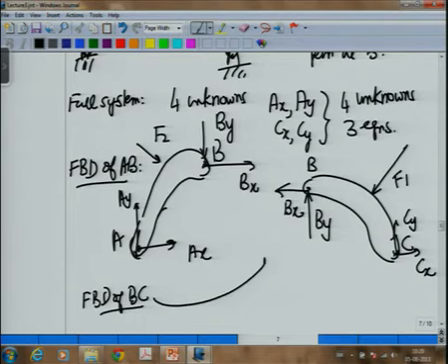Otherwise, the system would tend to move along that direction, and the unknown would become the acceleration along that direction, which is not known. So, actually this is all following from dynamics. I have put sigma F is equal to 0 here, actually it is equal to ma, and that also tells you why the forces are being applied if there is a restraint. If there is a restraint, you are preventing the acceleration, and since F is equal to ma, because you are preventing the acceleration, it is providing a force. That is the logic of saying that an unknown support provides a force if it does not allow movement, because F is equal to ma, you are forcing the acceleration to be 0, that is why the force has to be there. So, that was the whole logic.